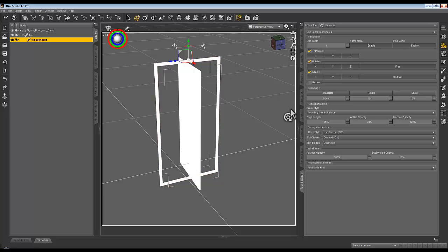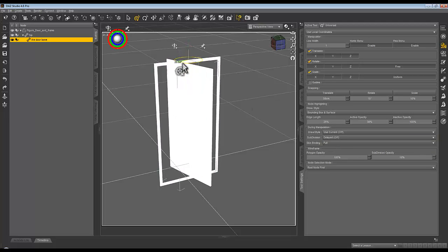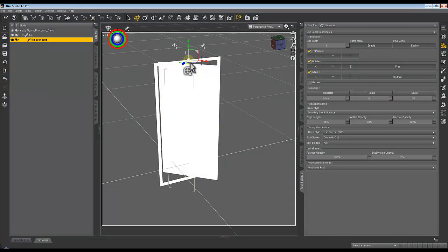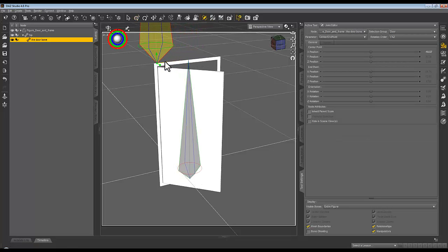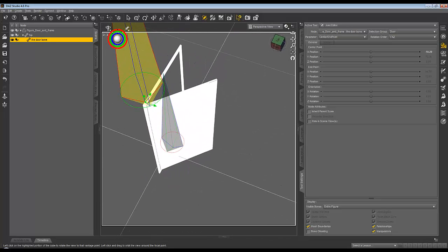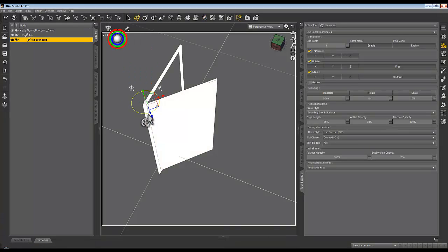it goes closed. But if you go to the tool settings here for the universal tool and change skin binding from optimized to full, then when you do the adjustment you can see the intermediate phases of adjustment. But at the moment it's rotating in the middle where the bone appeared by default, so to solve that problem go back to the bone editing tool there and move the position of the bone so it's over the point at which you want the hinges, and then when you go back to adjusting it, here we go, we've now got our hinged door in the door frame.